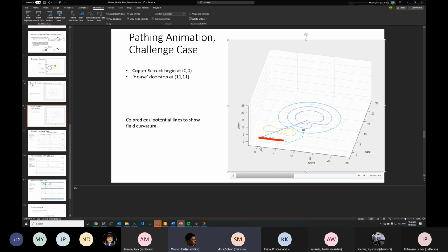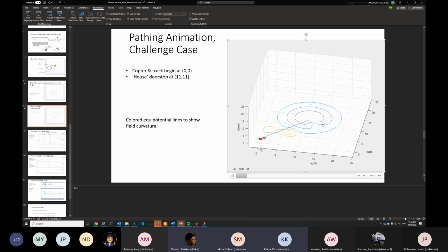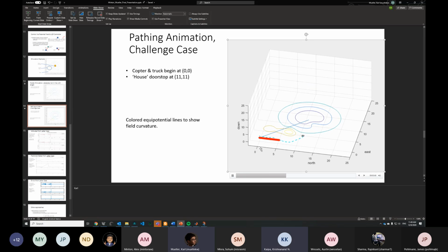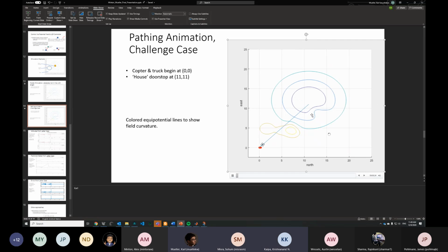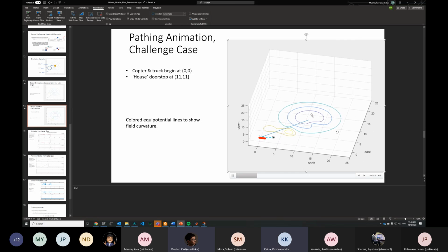So basically, the artificial potential field is also present on the direction of the return, even if it is a quick maneuver. The copter itself points back towards the truck, and in the case of the copter returning to the truck, I actually removed the initial goal potential contribution. So the only potential field left is the obstacles. So it navigates away.